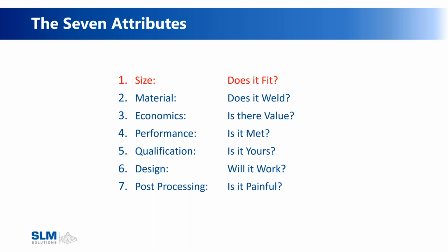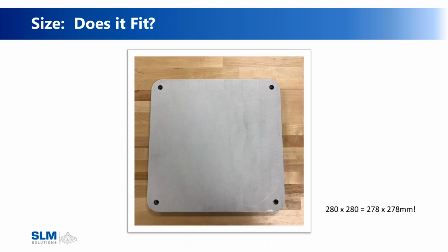That first one, does it fit? Does the part fit within the plate? So a 280, which you see here, the plate is actually 278 millimeters square. The Z height in the 280 is 365, but then we subtract the height of the build plate itself. So it's a 25 mil plate, we subtract that 25 millimeters. As you can see, there's area for bolt holes there, clearance, which ends up being about 15 to 20 square inches of material placed area removed.